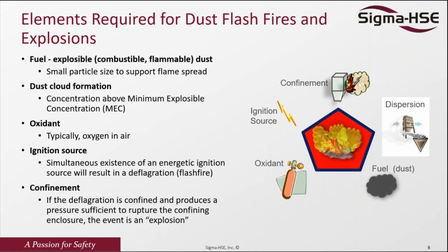Then we have this homogeneous ignition: the energy that we release will actually create a vapor, and the vapor will react with oxygen to ignite. So homogeneous ignition, when dispersed in the air, acts like a domino effect, where maybe the first one ignites and moves to the next, and then we have combustion. Each of this energy which is released can actually accumulate.